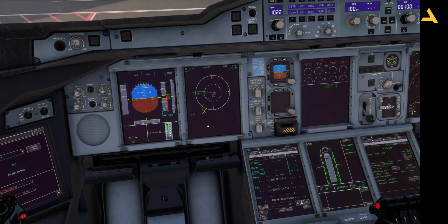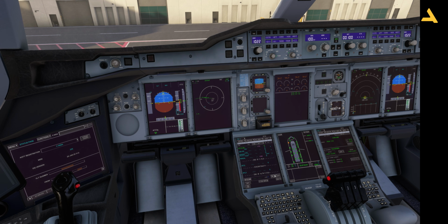So my purpose of using this kind of method was to just show you how you modify the flight plan. So remember this thing that for different airports, there are different approaches and different arrival procedures. This was for Islamabad. Maybe if you have selected an airport, it has a different approach and a different arrival. So you have to modify the flight plan according to your airport. So that's why it's really important to basically consult the charts. You should be looking at the STAR and the approach plate as well.